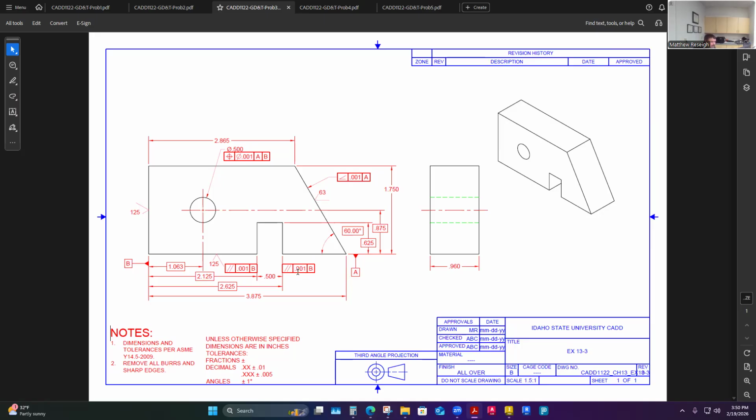But I'm going to use this same concept here, and apply that these are also in that 10 thousandths range. So what they say is datum B is that left side surface. I'm going to control how parallel this is. Yep, it's going to be another orientation control. I'm going to control how parallel that surface is to datum B, and I need it to be within 10 thousandths as well.